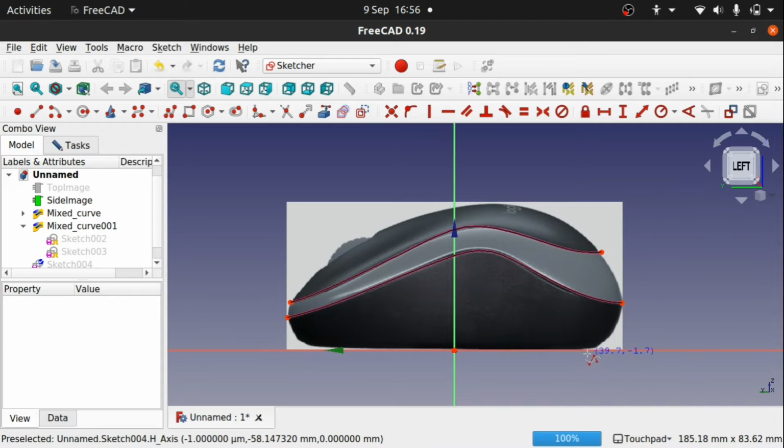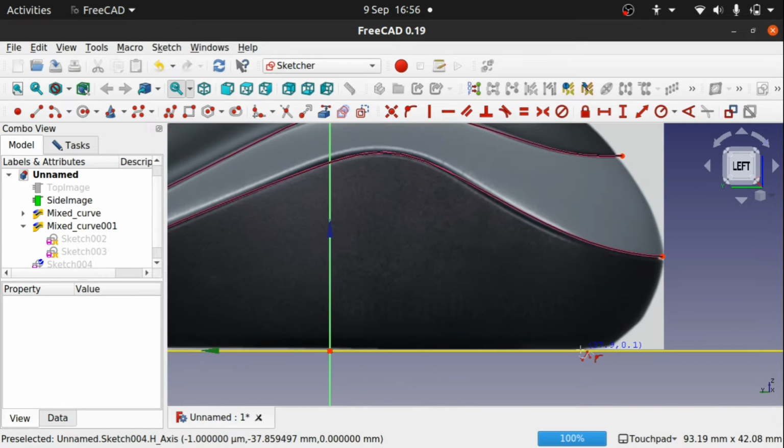and I'm going to attach myself to the bottom here, the bottom of this line. I'm looking to see where the mouse curves around and touches that bottom. And we're going to sketch all the way around that B-spline and connect up to that point there. Now I'm going to hit escape, and now I've got the B-spline tool back. So I've created one B-spline.